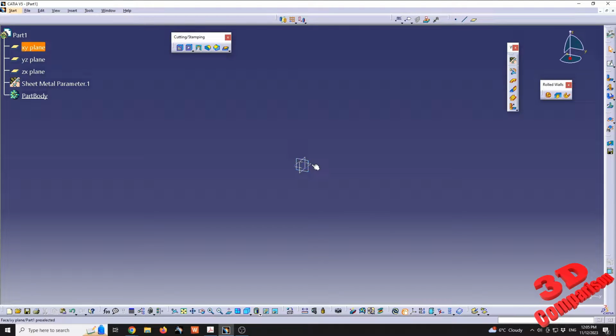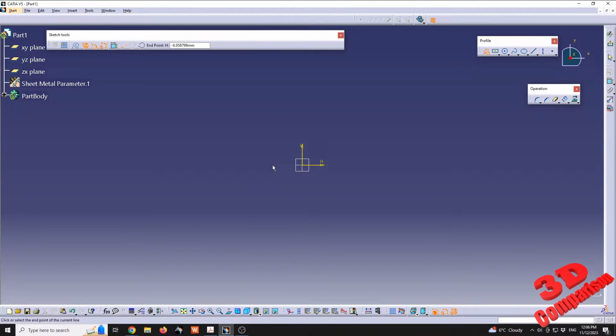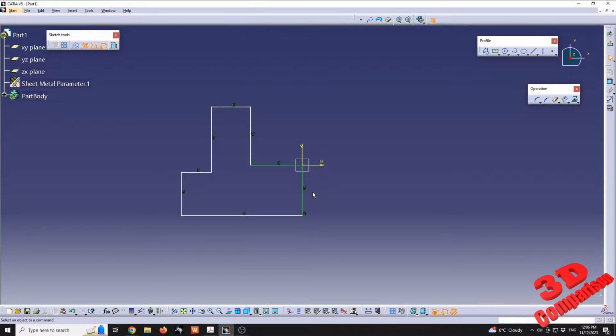Now for the shapes that can be added for the first wall, we are going to talk about the wall function over here. So we're gonna need a closed profile for this one. For the first case study, I will use the profile tool within Sketch, and I will draw the following shape. I will also close it over here on the vertical axis.